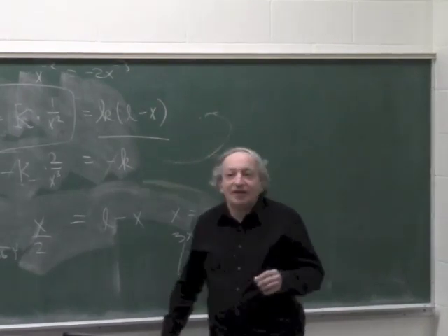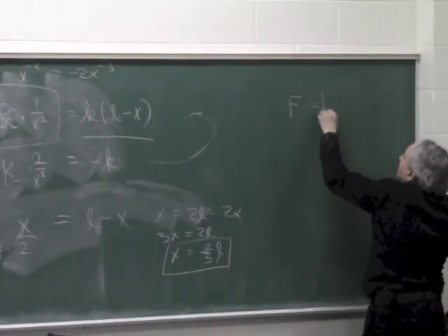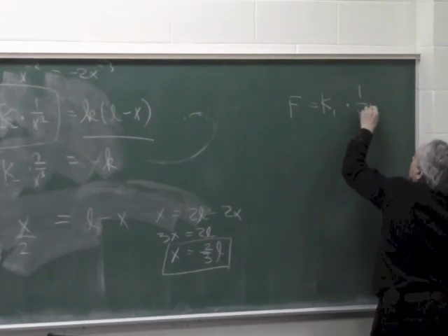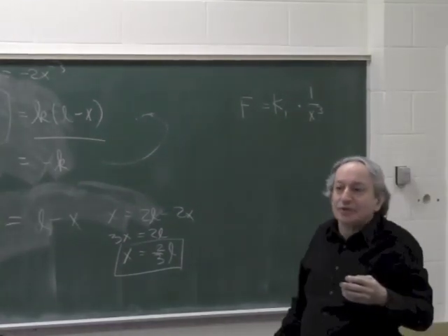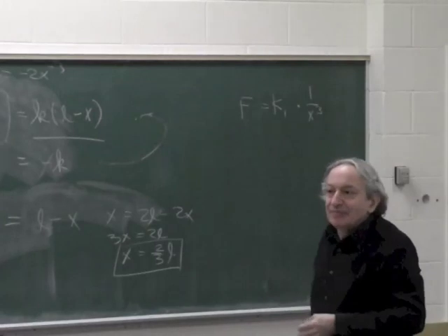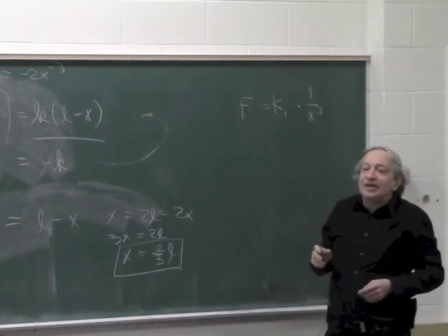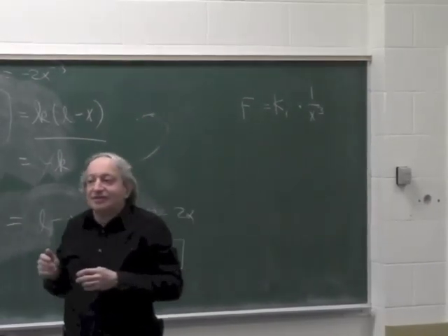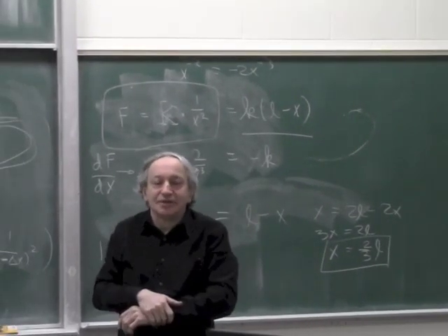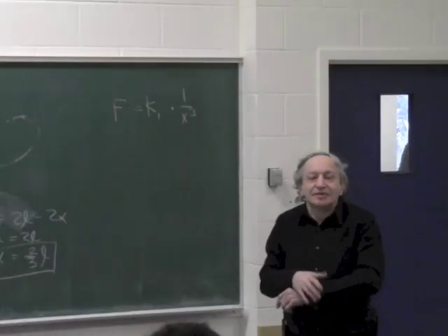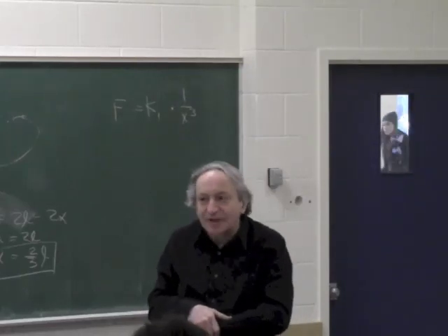Okay, now let's see if you followed carefully. What happens if I have an actuator where F is proportional, let's call it a different K, to 1 over x cubed? Because in theory you can build actuators which are not just inverse square law. You can make an actuator which is inverse cube, inverse fourth power. So if I have such an actuator, will it snap sooner or later than a moving iron actuator? In other words, will the usable range be more or less than a moving iron actuator? Okay, so what do people think? Pardon? Sooner. It'll be worse.